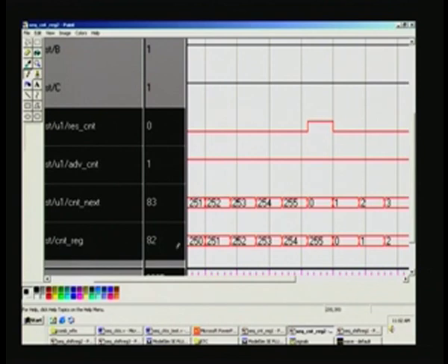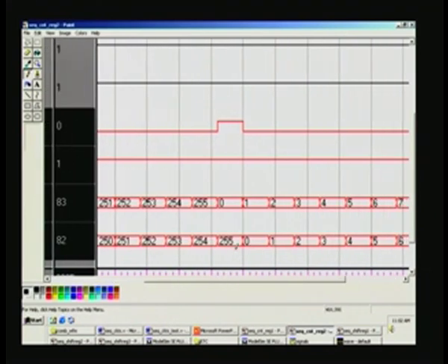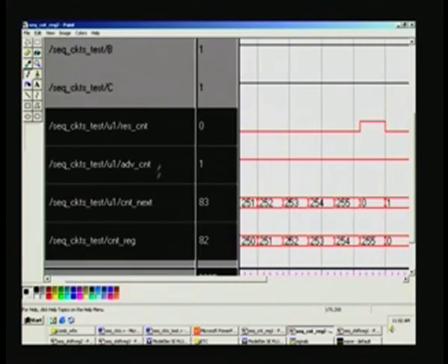This is the actual output that we desire, and when you see here it happens that 255 is here. This is for the count edge. That is when it touches 255, right. This being a combinational circuit, it goes high, for so long as it is 255. So, this is nothing but the reset counter. When it touches 255, the counter is reset. That is what we want.